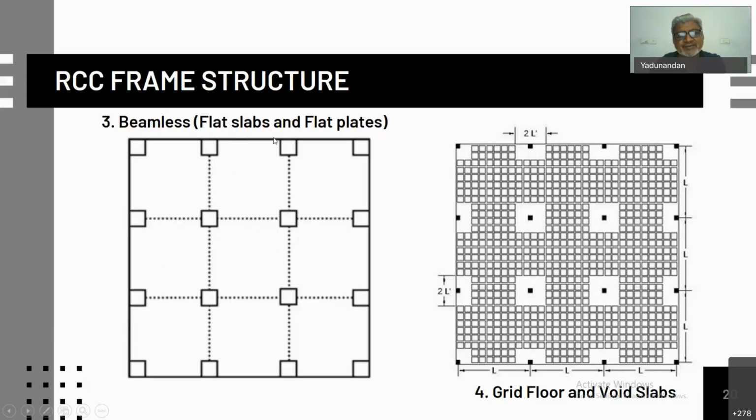It is commonly used for low-rise structures, and similarly for apartment structures and structures like that, where even the capital is not desired and the spans are quite small compared to the capacity of the slab, like 6 meters or 5.5 meters, where you can provide a square column plan. Then we do away with the capitals and try to provide a plate sitting over the columns directly, where the shear is taken care of by special provisions, giving a joint detail where the shear is taken care of by additional jointing mechanisms.